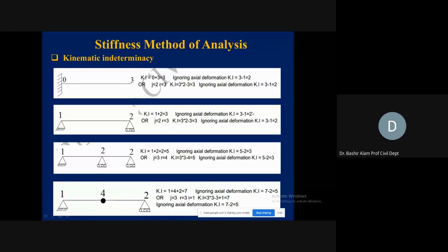If you want to go by the equation, now most of the time people forget the equation. So if you forget the equation, this is the option: you go by the observation. Now, j is equal to 2, this left hinge support joint and the roller support joint. Reactions are 3. Which ones are those 3 reactions? One vertical at this left support, one horizontal at this, and then one vertical here. So this is how we get these 3 reactions.